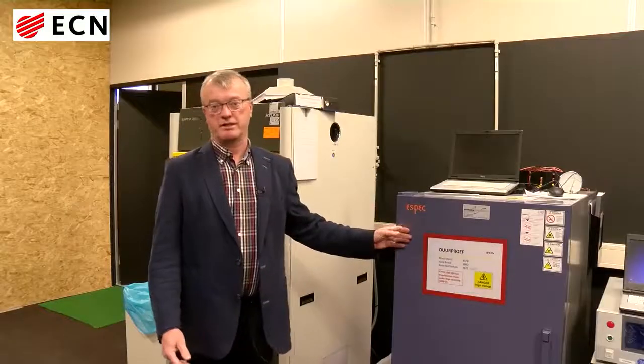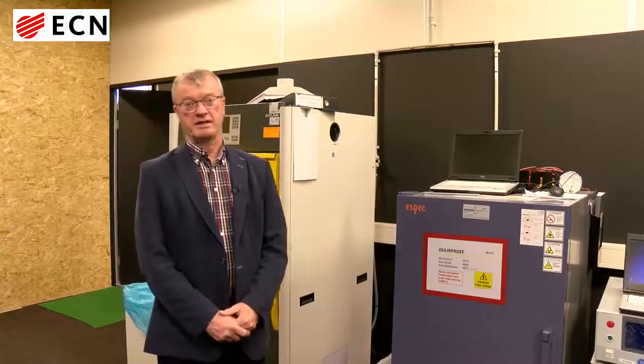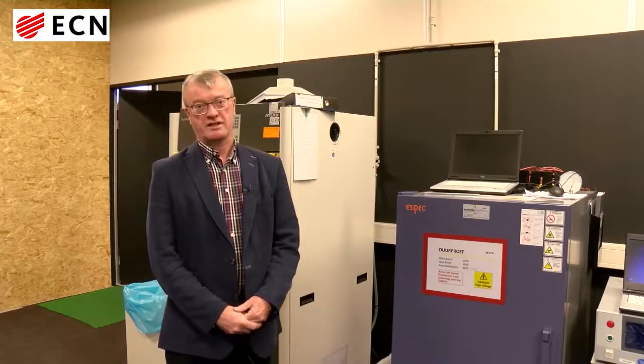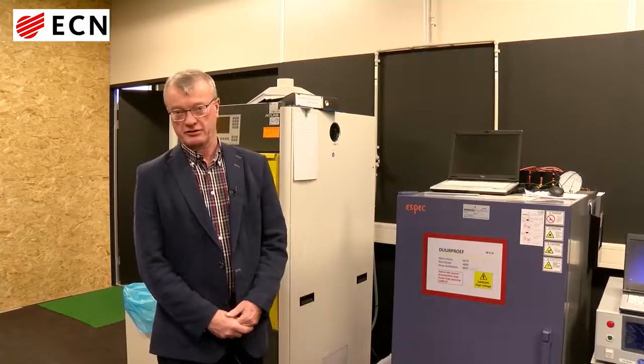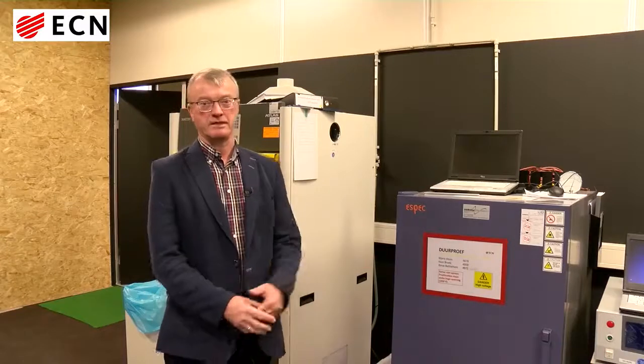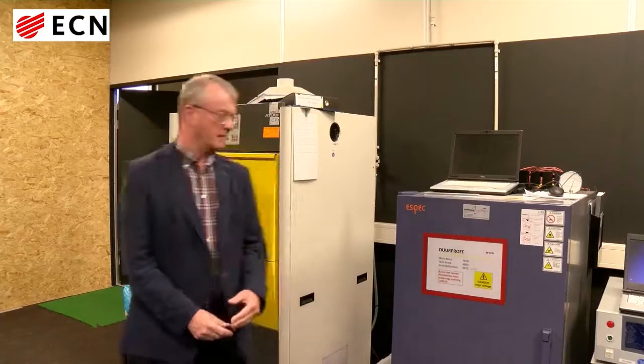In this chamber we are testing the degradation induced by a high potential in a PV system, especially the large power plants. The voltage can build up to 1000 or even 1500 volt, and here we're testing the durability of the modules with those high voltages compared to the bias volt, which is around 0.